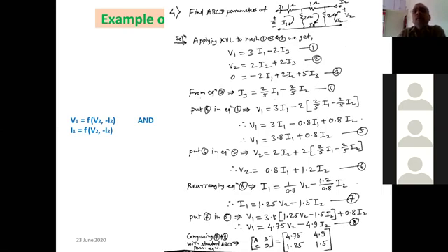Simply, this is a network having now 3 meshes. So 3 meshes are there. So 3 equations will be resulting after applying KVL to all 3 meshes. Okay. So I assumed I1, I2 and I3 are the currents in these 3 meshes, and the voltages applied, they are V1 and V2 at port 1 and 2. Okay. Now after this, I'll apply KVL for mesh 1, 2 and 3.